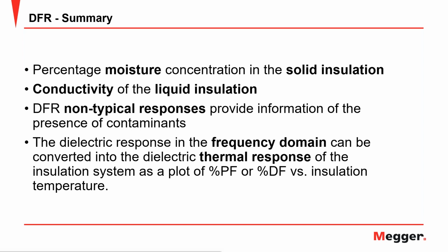So basically, just to summarize what we've been talking about DFR, the most important thing here is to determine moisture concentration in the solid insulation, then conductivity of the liquid insulation. Then we look into non-typical responses. And again, non-typical responses might be derived because of degradation of the insulation, or might be because of improper testing. So when you get a non-typical response, please get back to us. We will be more than glad to assist you with that.